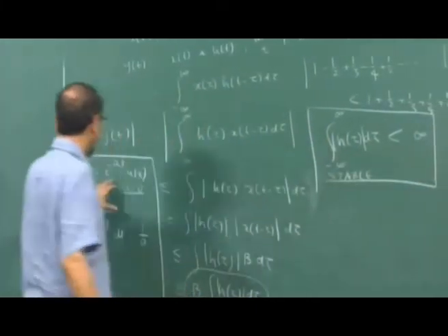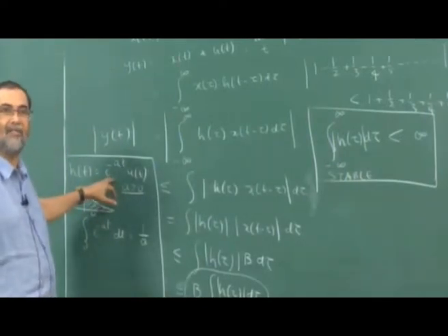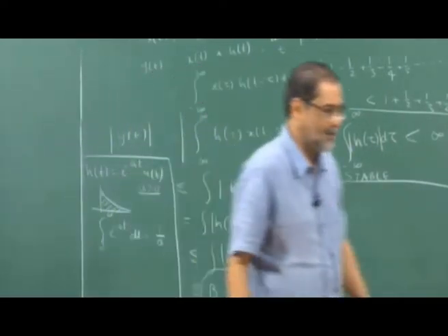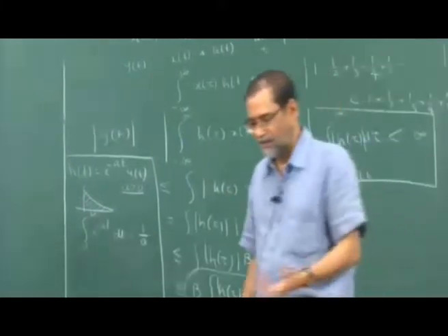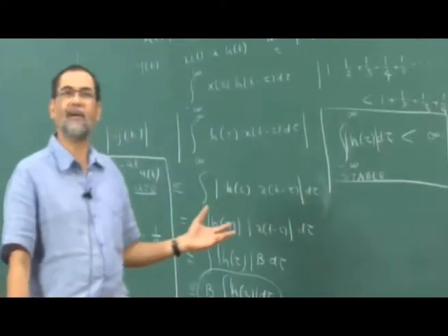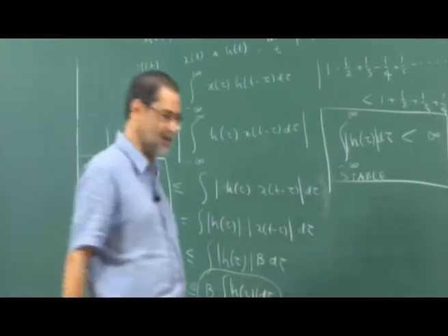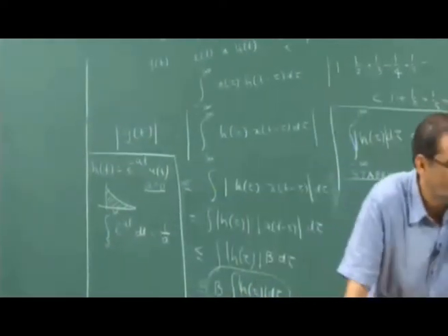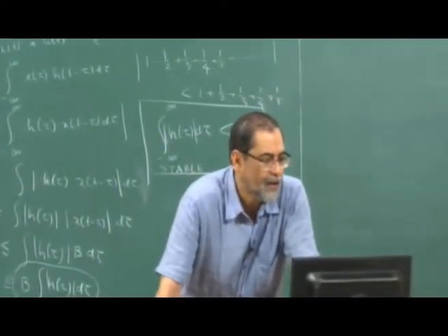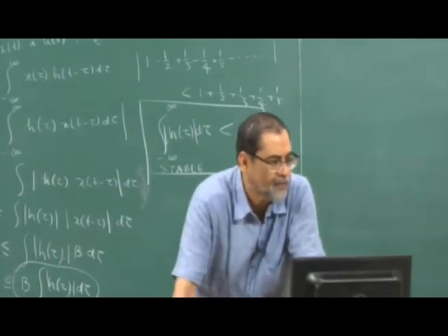So an impulse response which is decaying exponentially, and defined for positive values of time, is a stable system. Yes, the answer is yes, but that is not necessary. I mean, it's an overkill. If it is, it's okay. This is a sufficient condition, not a necessary condition, but nevertheless, it's a good thing to ask. So again from PSG Tech, e raised to minus a t u of t where a is greater than 0. Okay, so I already answered that. Then from PCP,